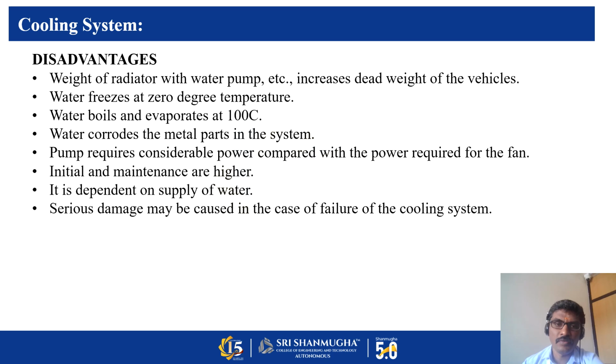Disadvantages: weight of radiator with water pump. Water freezes at 0 degree temperature. Water boils and evaporates at 100 degrees Celsius. Water corrodes the metal parts in the system. Pump requires considerable power compared with the power required for the fan. Initial and maintenance costs are higher. It is dependent on supply of water. Serious damage may be caused in the case of failure of the cooling system.